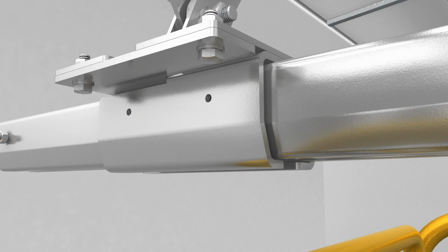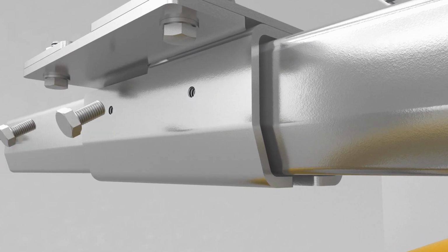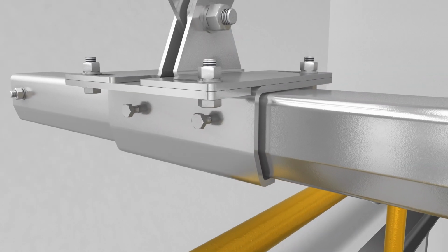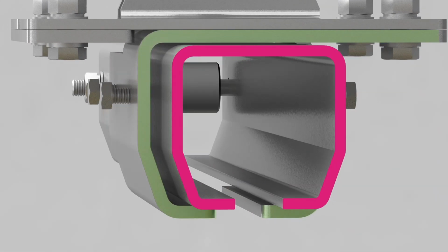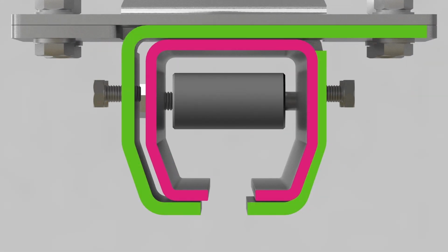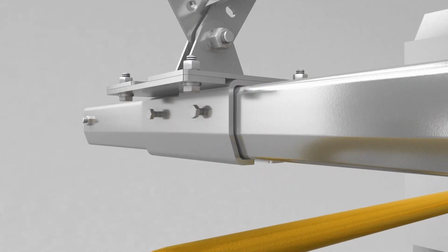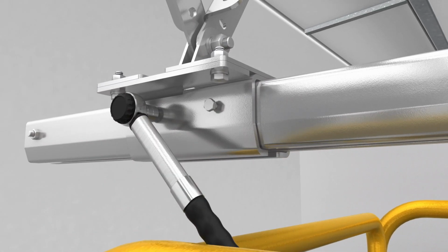To retain the rigid rail centrally within the clamshell assembly, insert 4 M10 20mm pinch bolts into the threaded holes that are located on the sides of the clamshell assembly. Care should be taken to ensure the individual pinch bolts are tightened evenly and sequentially so that the rigid rail is centralized within the clamshell assembly. Tighten all pinch bolts to the torque value shown in the torque settings table.